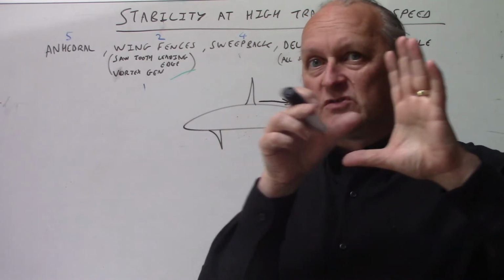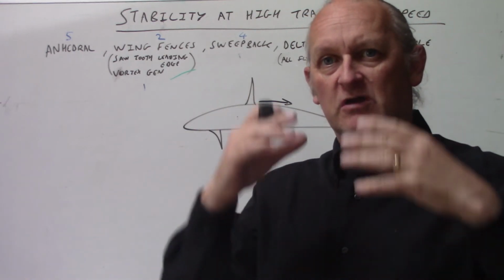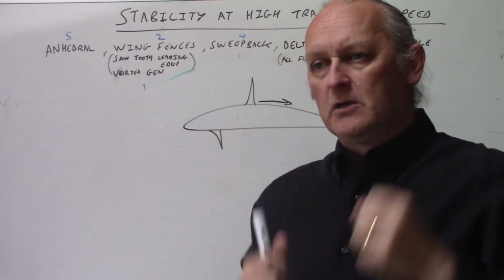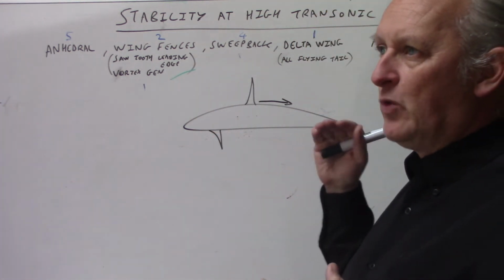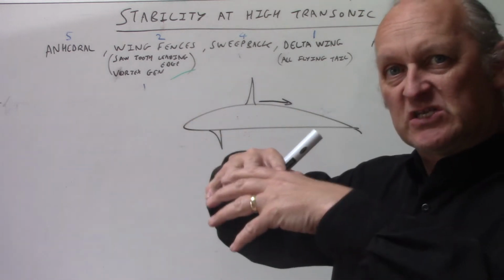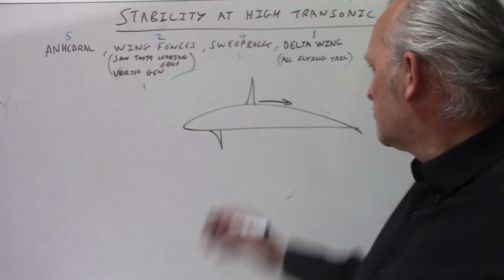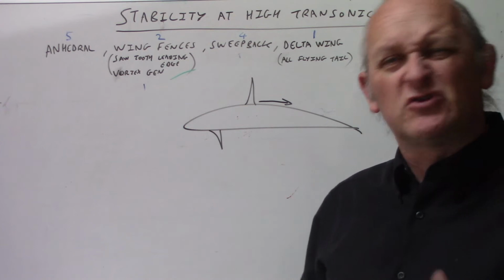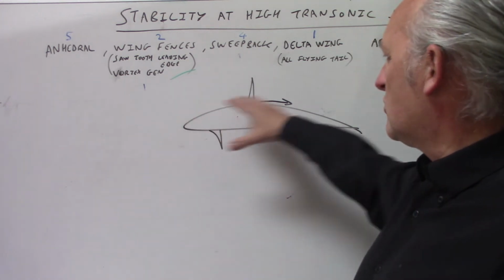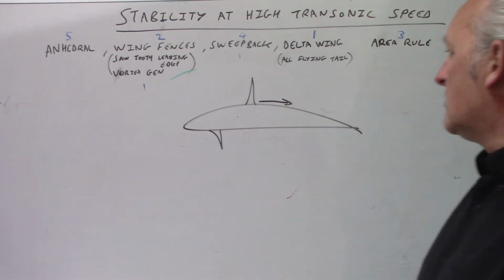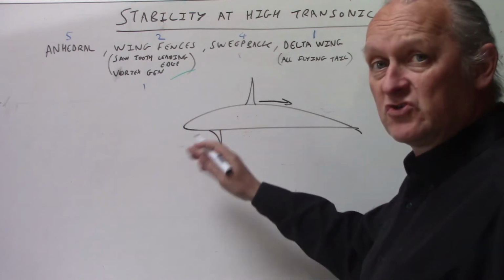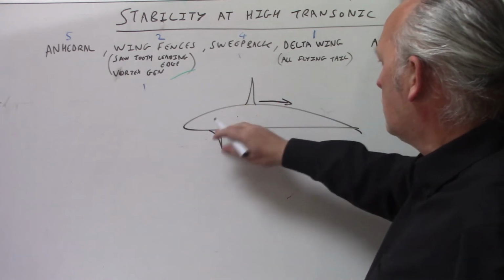It's to do with the cross-sectional area, and how the wing coming through the air is displacing the air molecules. So it will get stuck there a little bit, if we just say that for now. Again, it gets stuck on the bump. Because it's flatter here, the bottom shock wave will be smaller because there's not as much camber, and it will not get stuck on the bump.